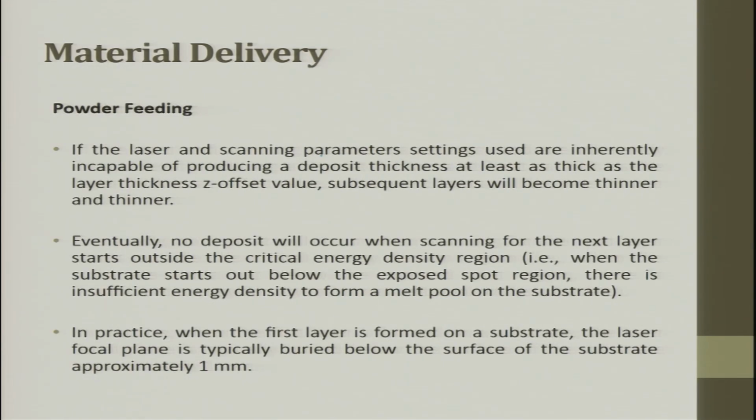To be noted, if the laser and the scanning parameter setting used are inherently incapable of producing a deposit thickness at least as thick as the layer thickness Z offset value, subsequent layers will become thinner and thinner.